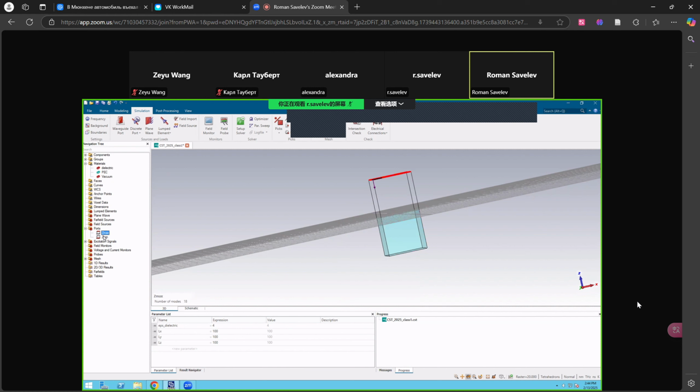So once we defined the unit cell, we have these Zmax and Zmin Floquet ports. If you click on, let's say, Zmax, you can see that by default you have 18 Floquet modes. You know that in this problem you don't have any diffraction, just the zero diffraction order.